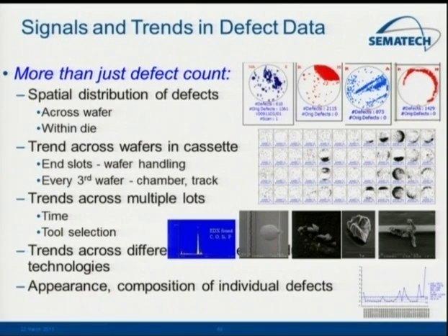Like this signature on the edge typically reflects if there's a door or something over here probably causing a problem. These are probably scratches. You may also end up with some defects that I mentioned are nucleation defects. Unfortunately, I don't have any of them there. So you're trying to take all of this data and correlate these spatial distributions, the number of counts at each step, and the trend across the different wafers, and put that together to achieve higher yield.